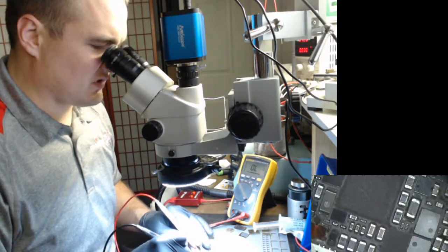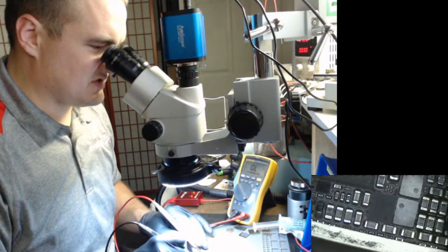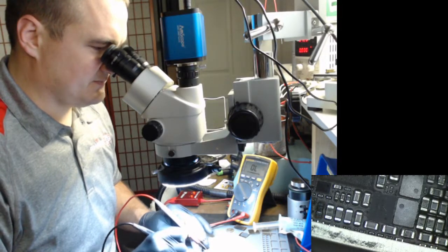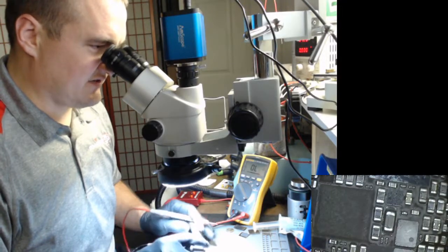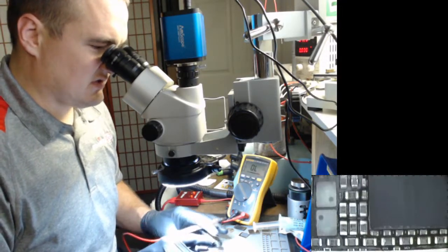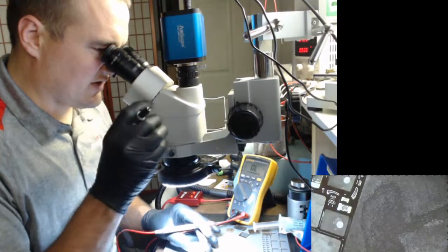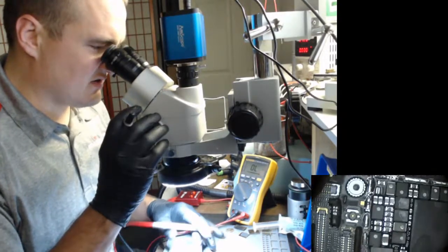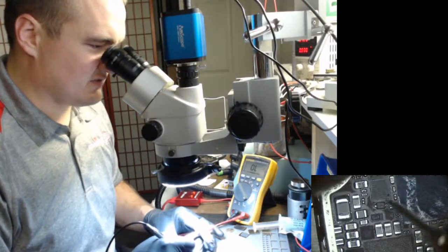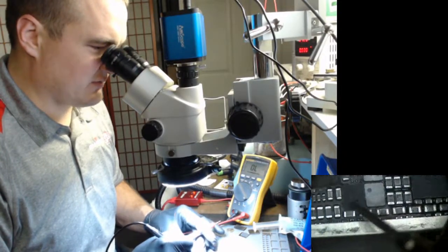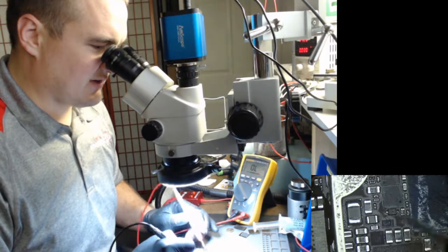I would actually be more inclined to suspect chestnut, because it's actually kind of giving out orders for what the display needs, what areas of the display need to be powered on, more so than backlight. I mean, backlight's just doing whatever it's told, but chestnut's actually making decisions about what happens.